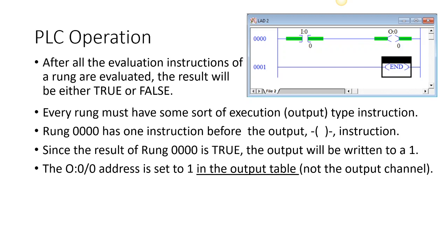And then when we're executing the program, we are looking at that spreadsheet and we're pulling out those pieces of information, and we're going to say, hey, was that channel on or off? And then we can actually test it to see whether it was off or on using different types of instructions. And based on those decisions, then we can write to output instructions.